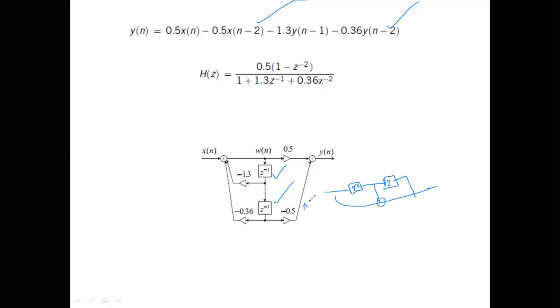So the time between the input and output here will have a delay of 2 clock ticks. When a valid input is given, for a valid output to come, there will be a delay of 2 clock ticks. Whereas if I go for a fifth order filter, between the input and output there are going to be 5 D flip-flops. That means when you give the input, by the time you get your first valid output, there will be a delay of 5 clock ticks.